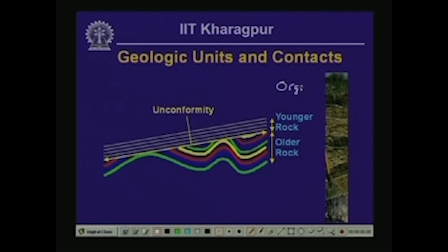So, this is the layer in which you have got some organics. The roots of the overlying vegetation actually penetrate this layer, and there is activity of different types of organisms. Then underneath that layer is a sequence of primarily granular soils of brown color, which extends up to the bottom where the shovel is kept. So, this is the layer of basically sands, silts and gravels.